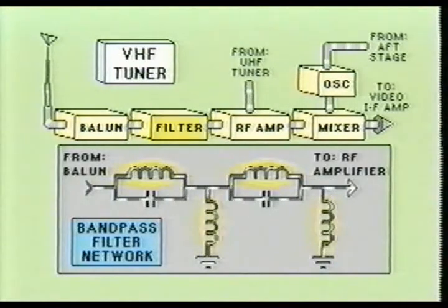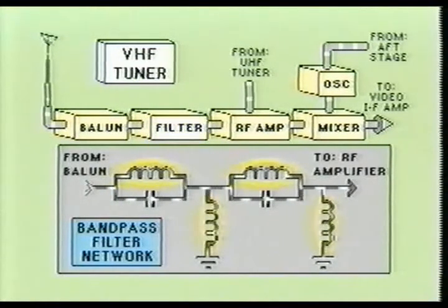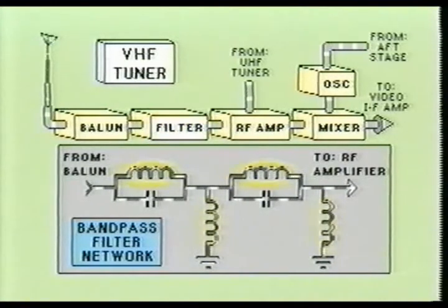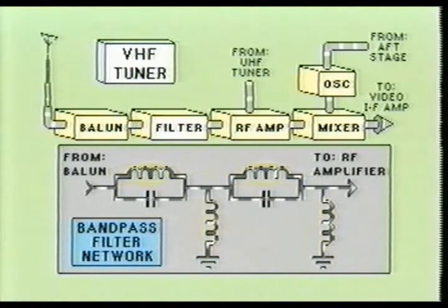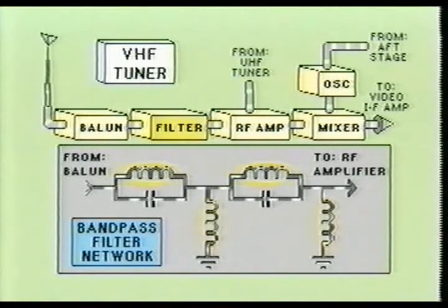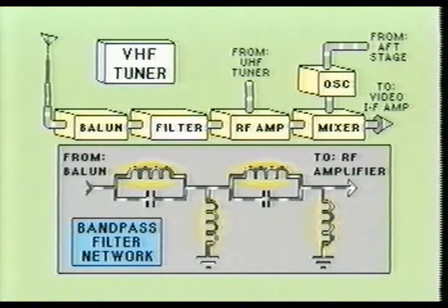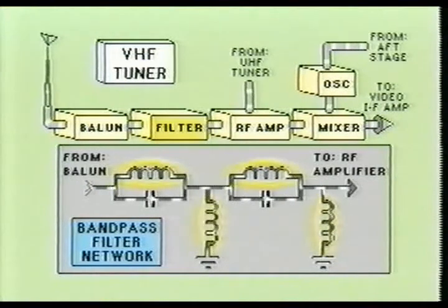The antenna filter circuit will consist of a series of resonant circuits that are used to prevent undesired signals from reaching the input of the RF amplifier section. This portion of the tuner could be considered as a pre-selector stage, which greatly reduces the interference from undesired frequencies. The tuned circuits in the antenna filter section will be set to resonate at the FM radio bandwidth and associated video IF frequencies.